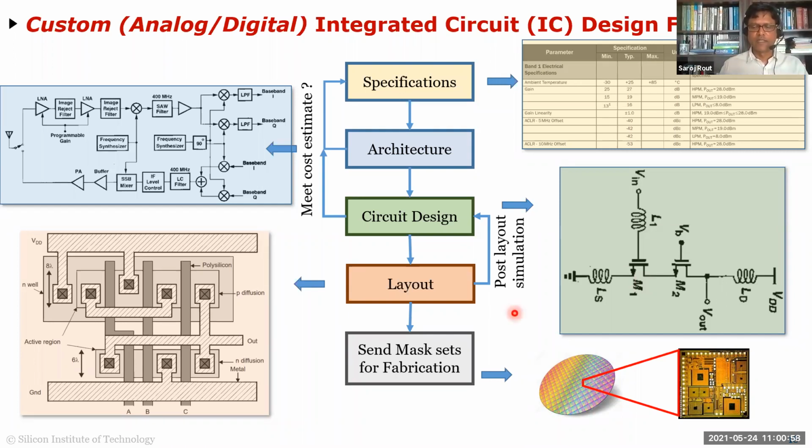But basically, you do post layout sim because there are a lot of resistances and capacitances which get introduced after the layout, which were not part of your original design here. And most of the time they'll kill your circuit. If your circuit is very high performance and you didn't do a good job of the layout, it'll come back and it'll not work. I mean, come back in the sense that when you do the post layout, it'll not work. And in analog, a lot of it you can't even capture in post layout. As a designer, you just have to be aware of it from your experience, right?